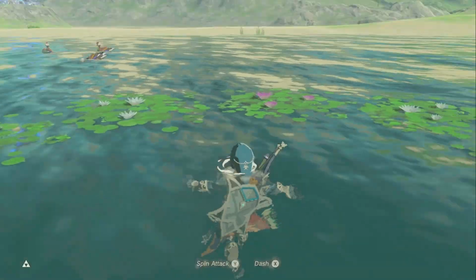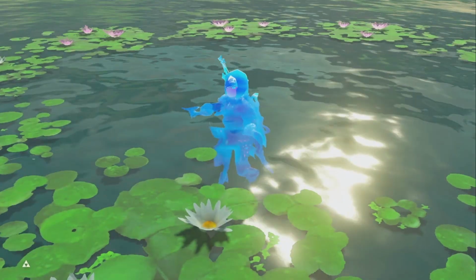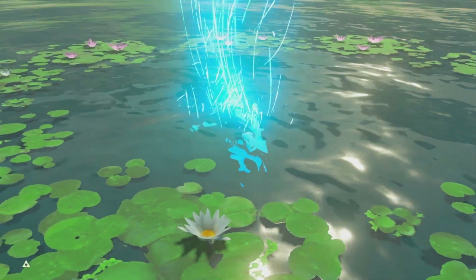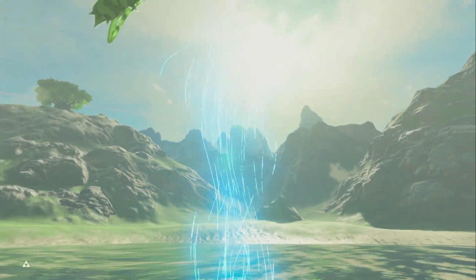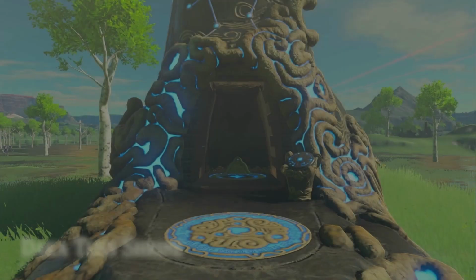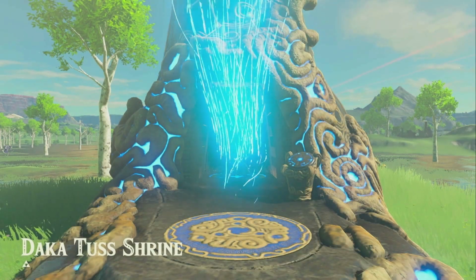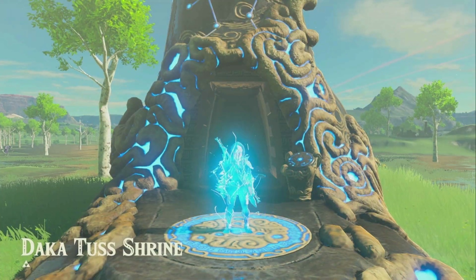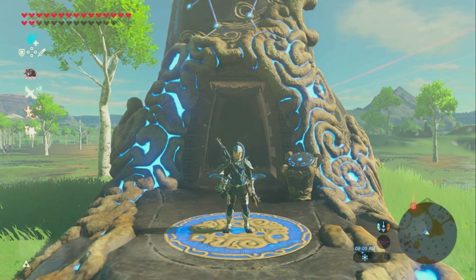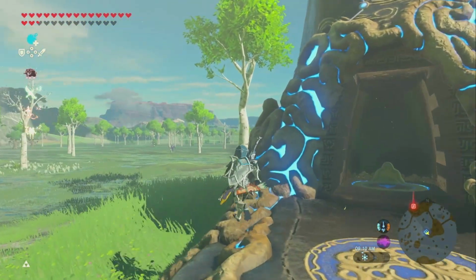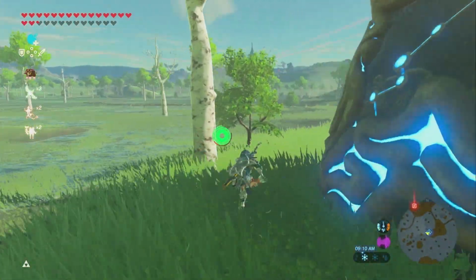Strategy. When looking into the burner compartment on a gas-fired water heater, make sure that the baffle has not fallen down onto the burner. You may be able to look around the draft hood at the top and see the top of the baffle. Where it is not intact, it may have fallen or may be missing.